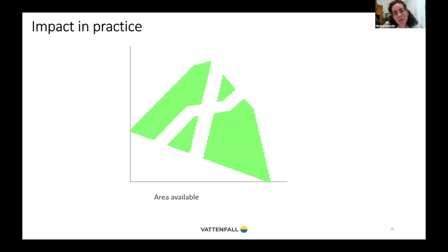What you can notice is that not all the area was available for building a park. You can see that there is kind of a white cross in the middle. In this case, it was because in the middle of the site, there were two huge export cables. You cannot build turbines on top of the cables, so this area is not available for building turbines.